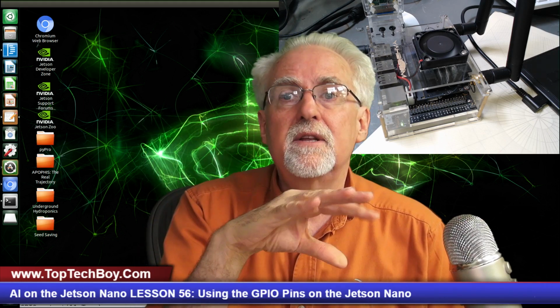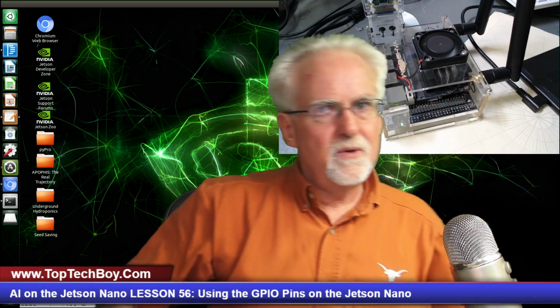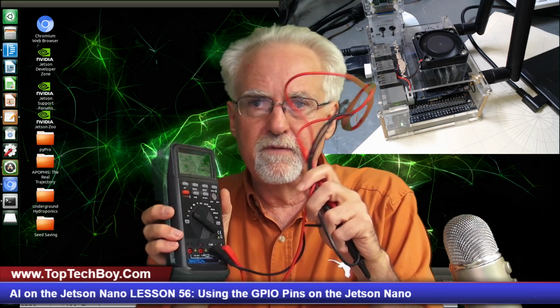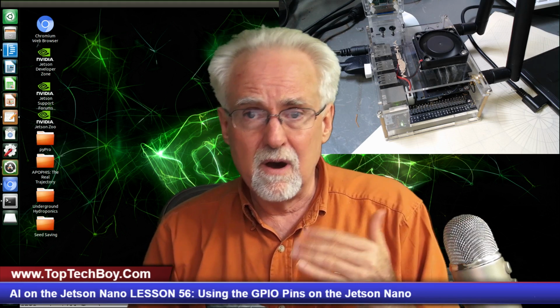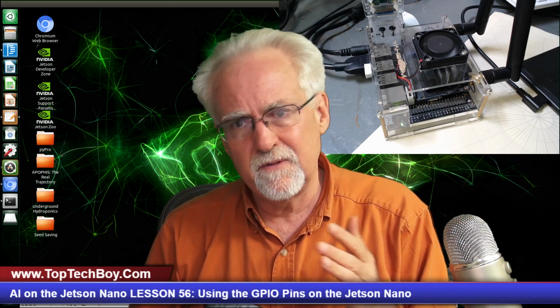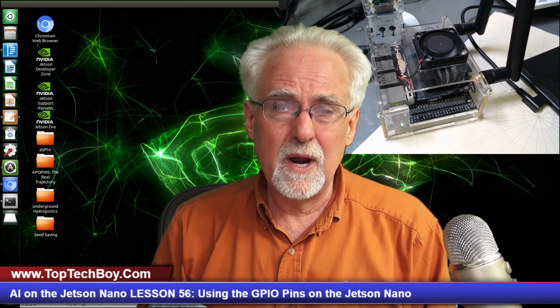The fourth disappointment that I had with the GPIO pins on the Jetson Nano is they are very, very sensitive to the capacitive load that you hook to them. So the first thing that I did was I tried to turn the GPIO pins on and off, and I had my digital voltmeter with these cables, and I could not detect the voltage coming on and off. Instead of going to 3.3 volts, it would maybe go to 1.6 volts and then wouldn't turn off, and it was just really incorrect behavior.